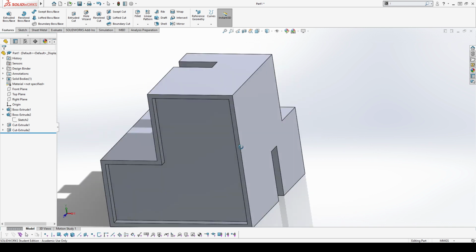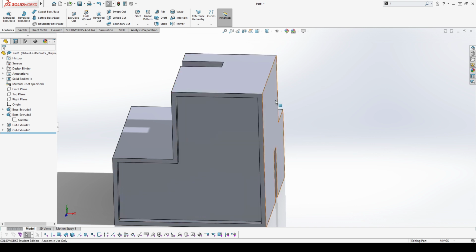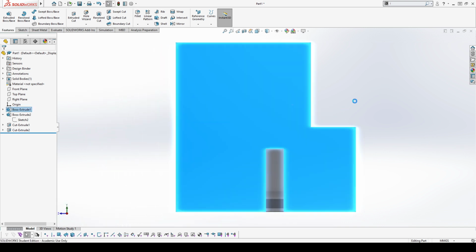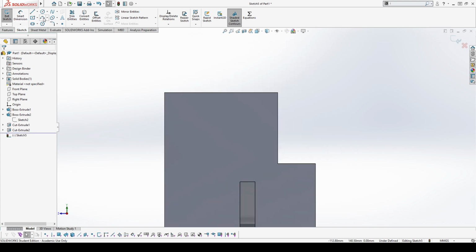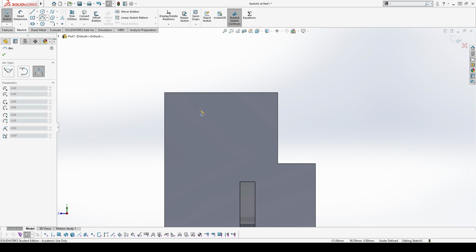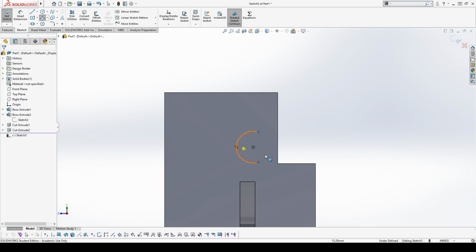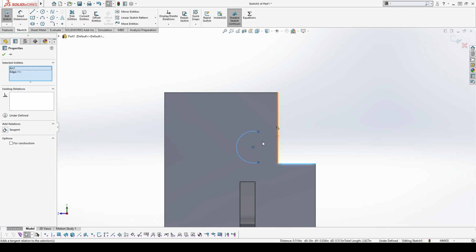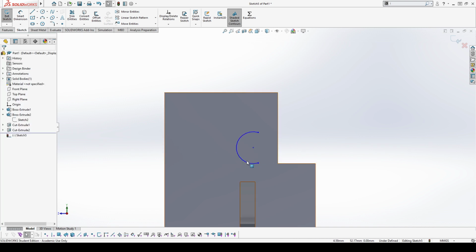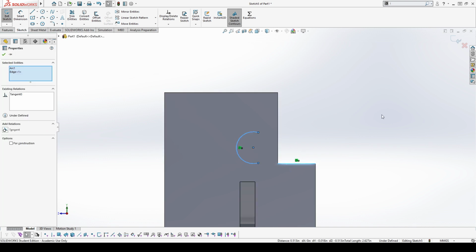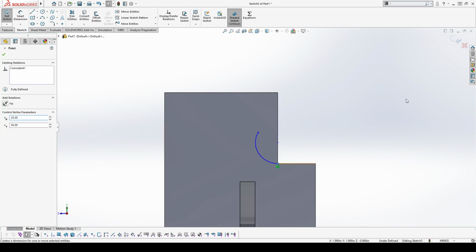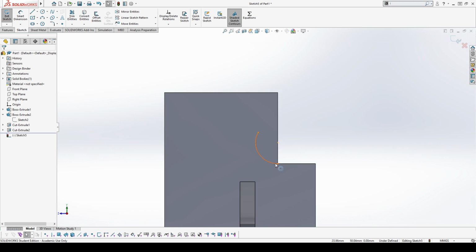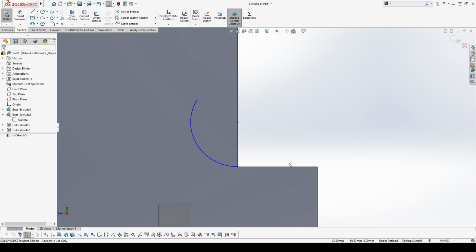And then just as one last thing, let's create another sketch on this plane here. Let's say that I wanted to create an arc like that, and I wanted it to be tangent to this line. Again, without bringing in the geometry of the sketch, I can still create relations. Yes, I can still create those relations there. Drag that in, and you can see that as that comes through, that's tangent to it. There is no line here within the sketch. Sometimes this can be useful just to speed up our design process or something else.